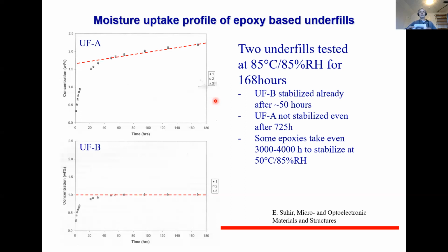But then they made the first prototype series, put these plastic boxes inside the 85 chamber, and when they put them in, they were the size of a cigarette box, and when they came out, they were the size of a matchbox and looked like raisins. So they had squeezed completely. And then they came to us and asked, what does this mean? Because in the specification, it clearly says that glass transition temperature is 90 degrees, and we are testing it only at 85 degrees, so it should withstand.